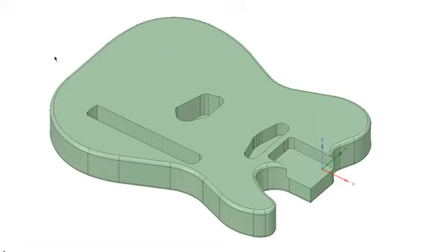The accuracy of the point cloud data comes in the number of points that you capture. You could capture with a hard probe points that are within plus or minus 1,000, but if you've only got 3 points defining a surface, it's very difficult to know what that surface is doing between those points. So the laser line probe very faithfully represents the exact shape of that surface, based on the density of the points that you have. I hope that goes some way to answering the question.